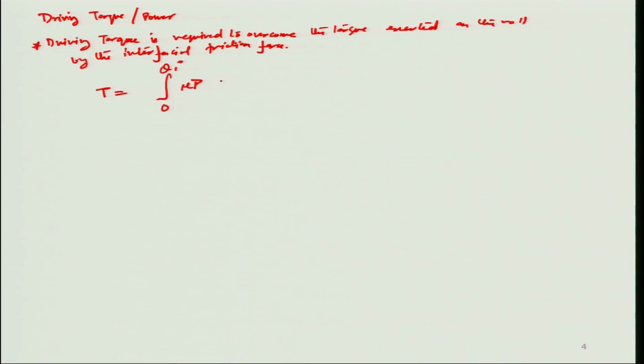which is actually equal to the width of that element, one unit width in the z direction. So you have r d theta times 1, times, because it is a torque and the torque is really played because of frictional force which is tangential to the roll surface at the center of the roll, you multiply that with the torque radius r in this particular case. And we can easily, because you know this p value would change its properties before and after the neutral point,